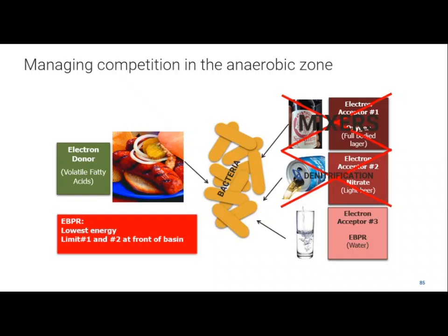All right, so that's what we do. We put in mixers at the front of our basin, so there's no oxygen transfer. That's a simple one. You just take your diffusers out and put in mixers. Mountain Creek just went through this, and we're in the process of doing it. And you just don't have aeration. Well, I guess you had surface area. Anyway, you just put some mixers up front.